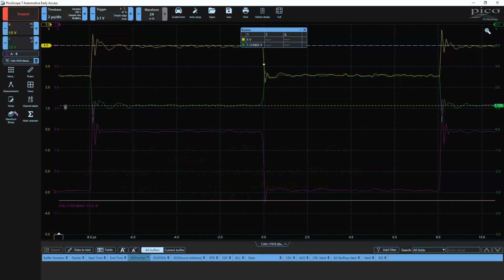That means it's going to get dropped out onto the CAN bus. I don't know, some people feel that they can look at CAN voltages with a DC multimeter and pretty much diagnose a CAN network with a DC multimeter. Okay. I've never been able to do that.